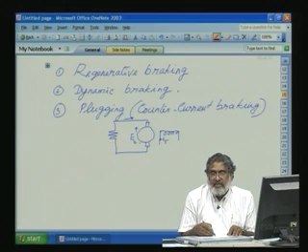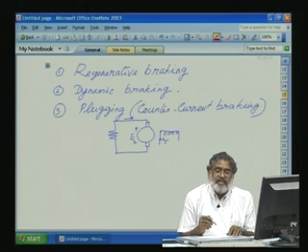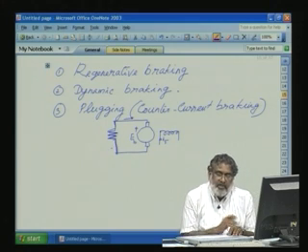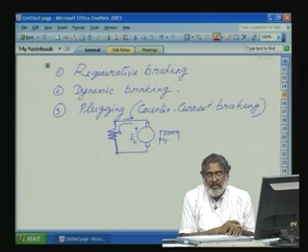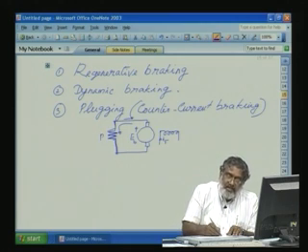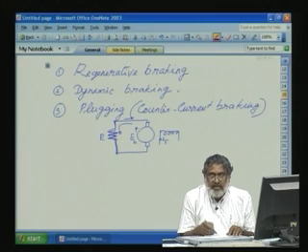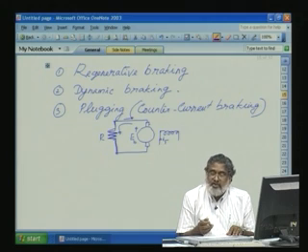Now, there is a back EMF here, and we want the load to supply current back to the system. So, sensing this 0 current, we can immediately switch on a resistance here, so that the current will reverse. This current depends on the maximum rated current. If the resistance is very small, the current will be very large, so the system could quickly come to a 0 state, but that is not possible.